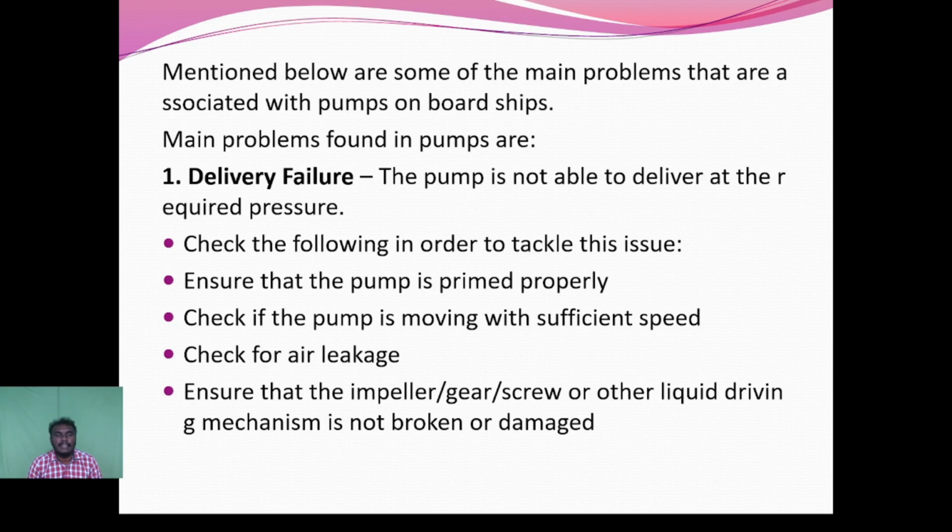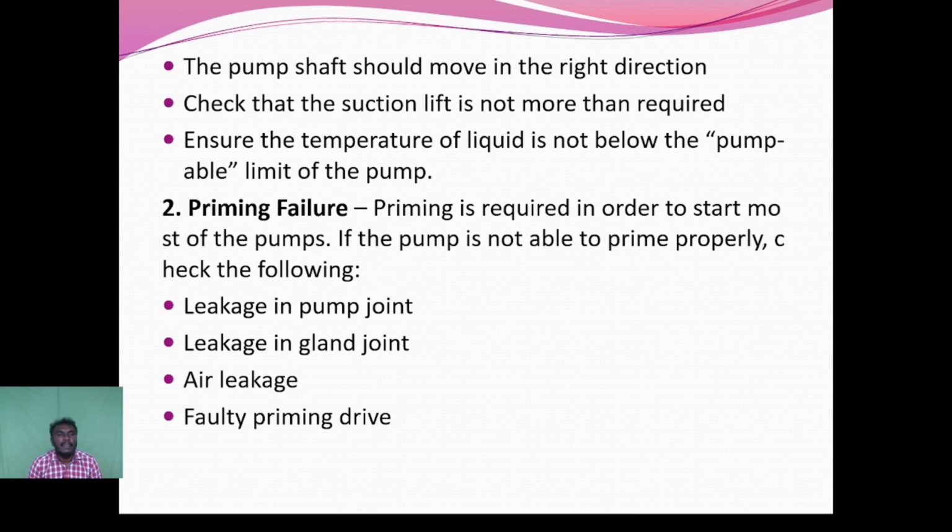To tackle this issue, check the following. Ensure that the pump is primed properly. Check if the pump is moving with sufficient speed. Check for oil or air leakage. Ensure that the impeller, gear, screw, or other liquid driving mechanism is not broken or damaged. The pump shaft should move in the right direction. Check that the suction lift is not more than required. Ensure the temperature of the liquid is not below the pumpable limit of the pump.